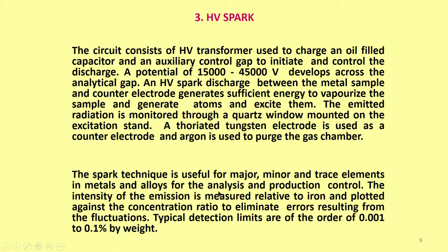So, the spark technique is useful for major, minor and trace elements, but normally what we do is we measure the intensity of the radiation with respect to a reference sample. Otherwise, the spectroscopic technique is always a technique where it is only relative. So, you have to have something on which you depend, and that dependent is iron.